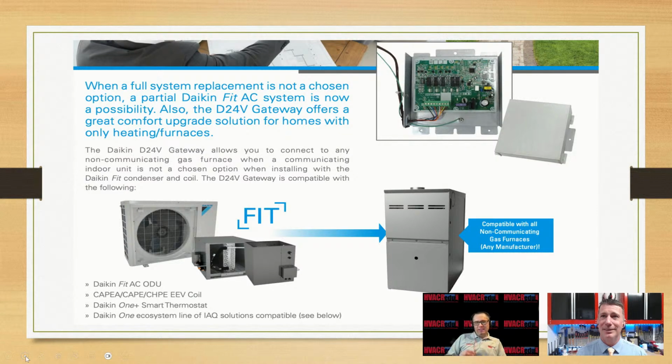And you get the efficiency of that variable capacity outdoor unit? Imagine that. A lot of our AHRI ratings are for a time delay relay, so that gives you an AHRI rating for an inverter system with a time delay relay, not necessarily variable speed motor. So I wouldn't think we get the total efficiency, but you still get to use the component.